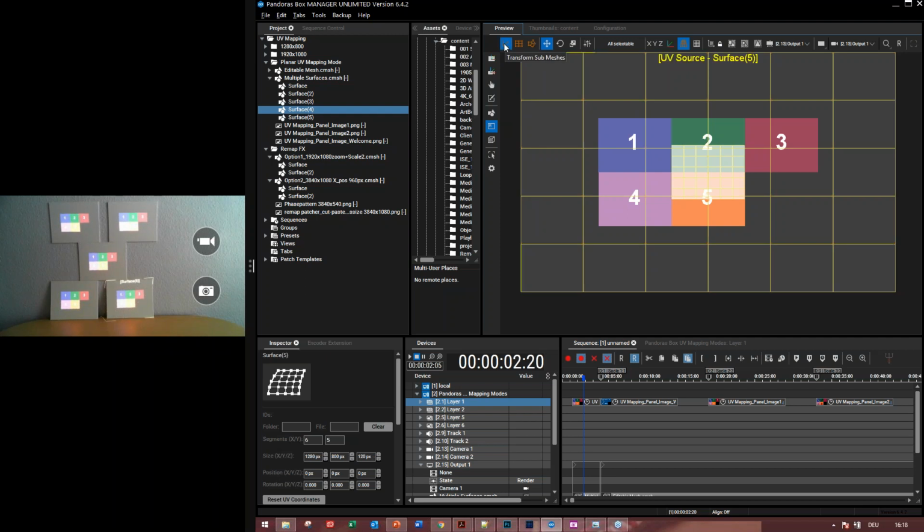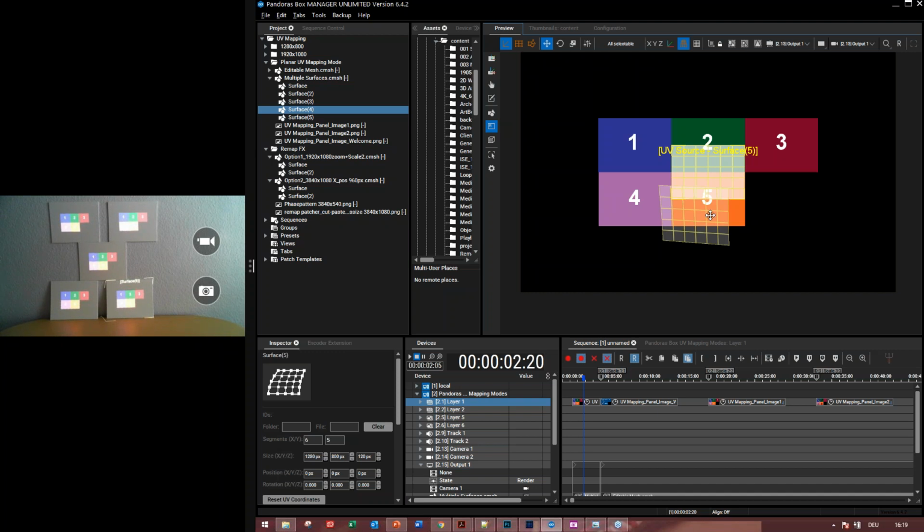Next thing: if I go again to the submesh modifier and click on apply planar map, you will see this is my surface. It has jumped to the original position of my editable mesh file, and it will just change its size to the same size as the editable mesh submesh.